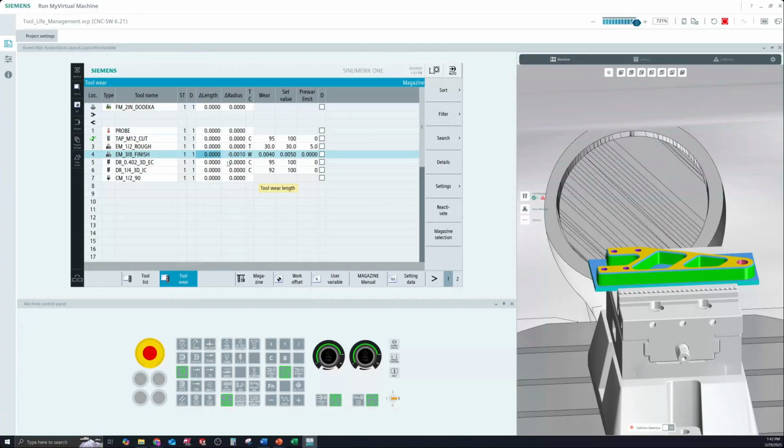So if I put -1 thou here, you see it stays at 4. It's not going to compound on each other. And the sign doesn't matter. It doesn't matter if it's negative or positive. I can change this to 1 thou positive, and you see the number doesn't change here. The only thing that matters is it's looking at the largest number here, or I guess the smallest if it's a negative. So that's the only thing that's going to change this.